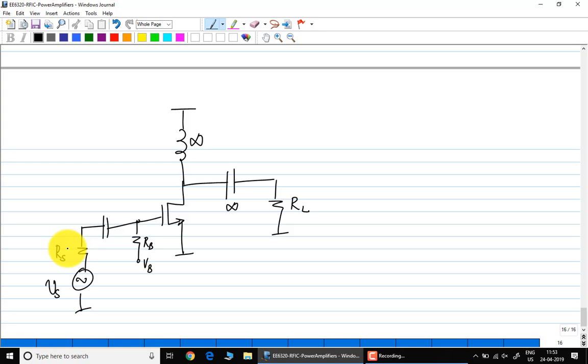Source degenerated. So he's suggesting source degeneration. Let us see if that will work for us. He's suggesting an LS that will give you a real part of 50 ohms. Okay, you can do it like an LNA. You put an LS, source degeneration, this is omega t times LS, and then you will add an LG, right? You could do this.